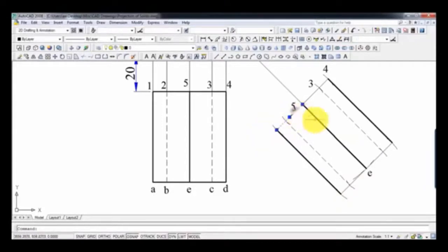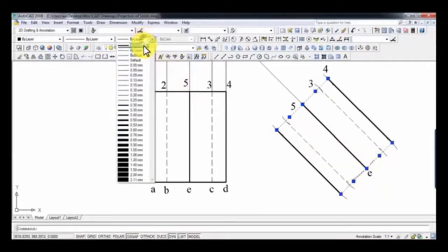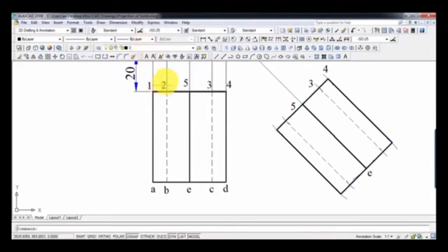So fine guys, this is how you can actually recreate the top view from step number 1 into step number 2 by ensuring that it makes a certain angle, 45 degrees, with the vertical plane. So that's exactly how this task has to be accomplished, and now I'm going to write them. This is point E and this has got to be point A.